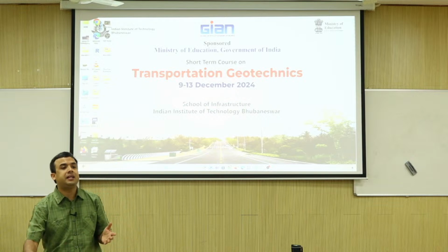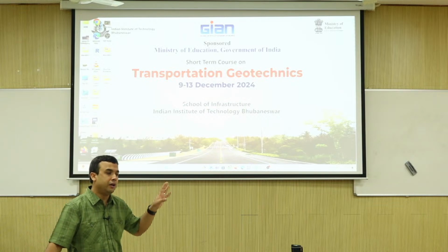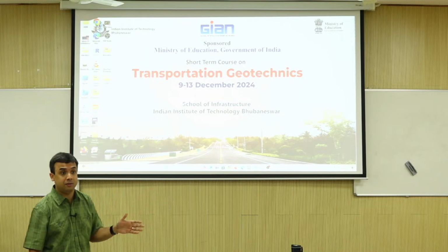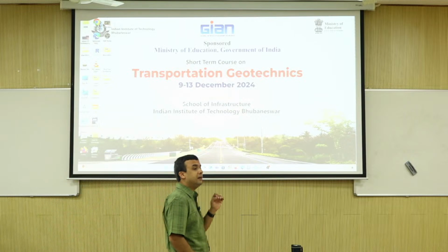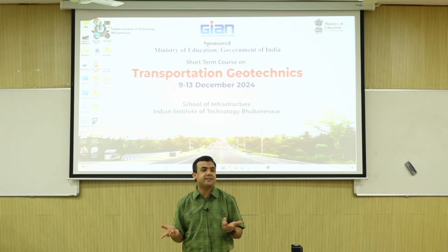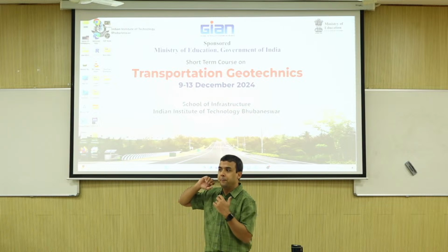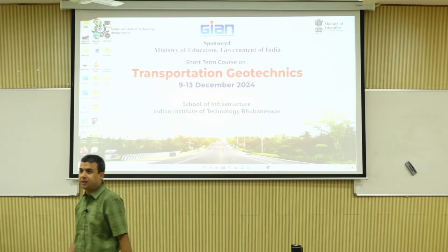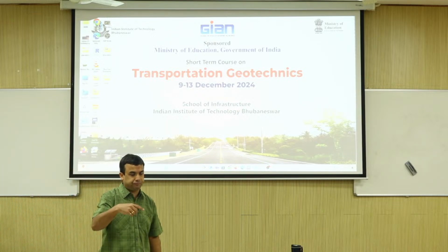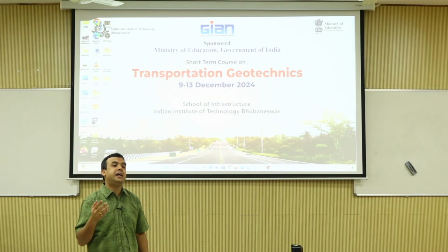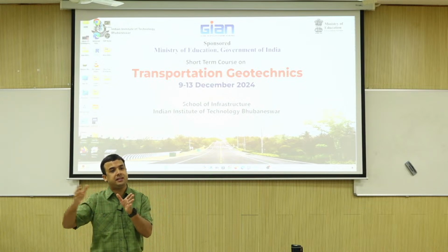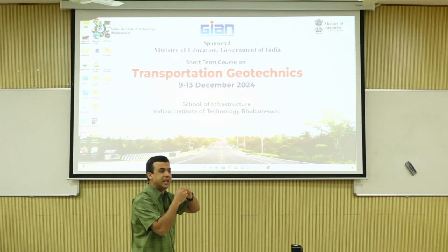And after that, one unique thing about railroads, at least in North America and Europe, is the inspection is very regular, extremely regular. You'll be surprised by the technology that gets used to regularly track it. And that is because the stakes are very high. The moment you have a derailment, you're talking millions and millions of dollars and people dying. So it gets evaluated, and then depending on the track location, the ballast can have different things. So ballast undergoes what is known as fouling. I told you, right?